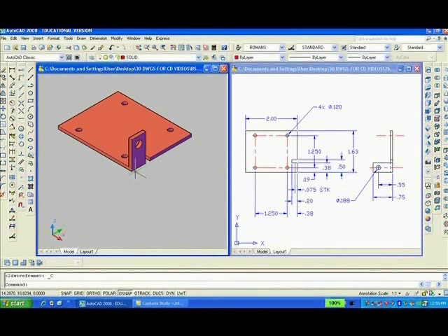It looks okay, but it should have a chamfer radius on the outside. When you bend material, if the material is thin, you can have a sharp corner on the inside, but the outside still has got to be a radius. So I'm going to type F, enter. I'm going to select that corner. Radius is 0.075, the thickness of the material. Enter. It says select an edge. Well, I already have, so I'll just hit enter, and we have it.